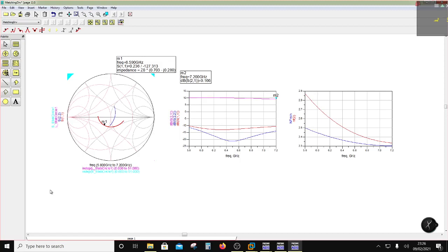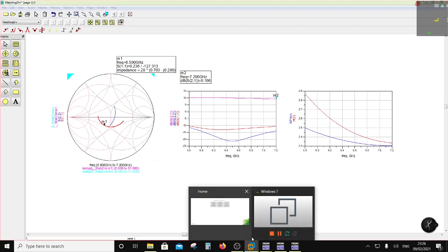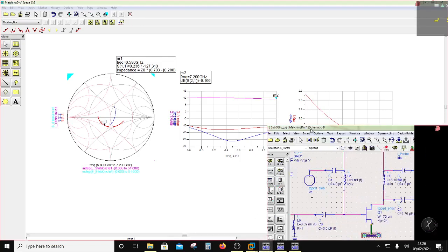Okay, for a LNA I will bias it at a much lower current, and when I bias it at the lower current, my noises, which we talked about in the previous session, are going to be less, and this thing is going to go down. Another way to bring down noise would be, I will just give you a very short example.